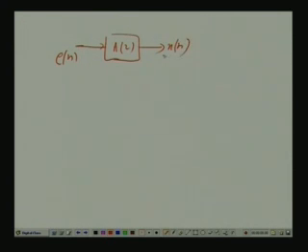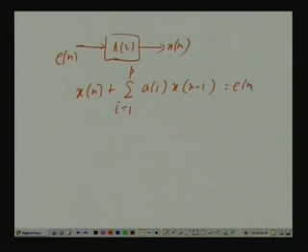We are considering either AR modeling or the linear prediction problem. In any case, we have got this equation, say a pth order problem, with e(n). If it is a linear prediction problem, e(n) is orthogonal to the past p samples, that is x(n-1), x(n-2) up to x(n-p).